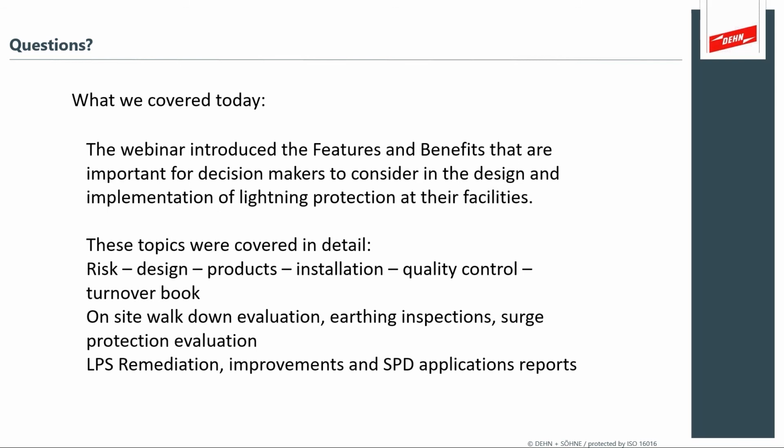Well, I think the concern about a type A system on a large interconnected plant like a water waste plant is that if you have type A electrodes scattered throughout the plant, each of those will be adequately protected, but you'll have interconnected lines between them. And now you have an earth electrode that isn't connected to the other part of the plant.